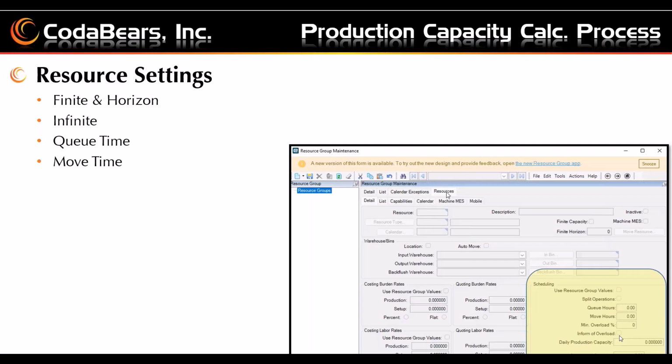Michael Cromer's got a question here. Is it possible to split on a shift change? That, I think, the scheduling engine's going to choke on. In the Epicor scheduling engine, some of the versions have a problem with shift changes. Or they don't look, if we're doing capacity scheduling, at the fact that, hey, I've got someone in second shift that can continue working on it, so it only scheduled the job for one shift of a 3-shift day.